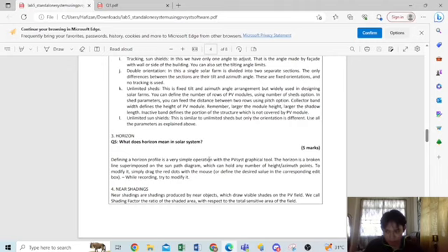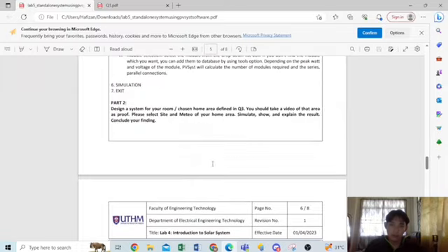To optimize the performance of the solar system, it's important to ensure that the solar panels are installed in a location where they can receive direct sun for most of the day and where the horizon is unobstructed. This can be achieved by selecting a location with a clear view of the sky, avoiding areas with tall buildings or trees, and positioning the solar panel at the proper tilt and angle. Next is part 2.